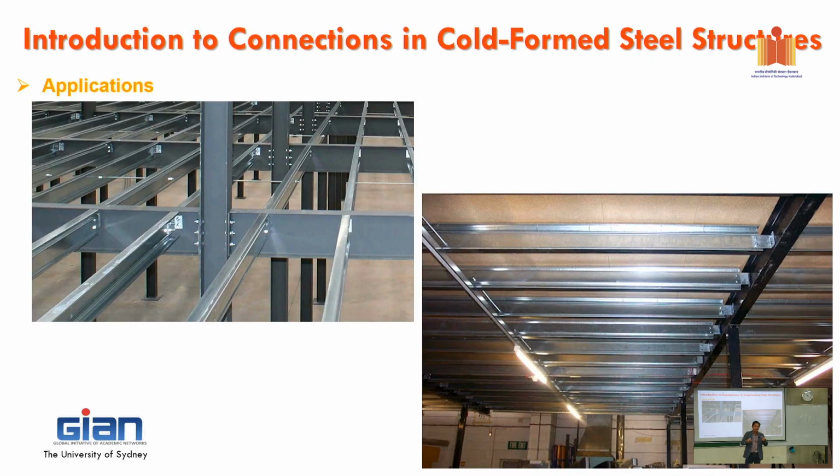I'll show you a couple of applications of why they're using screws, which are a lot faster. The second is the screw. With screws, you don't need to pre-drill. You don't need to have the pre-drill hole before you bolt it. Because of the bolt, you need to pre-drill it. So normally, in the standard and in practice as well, you need to drill the hole bigger than the diameter of the bolt for installation. Otherwise it's hard to fit in.